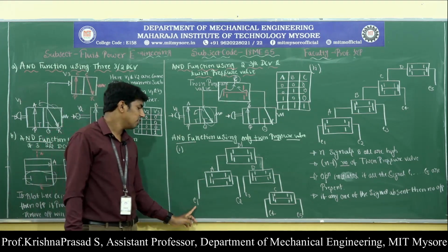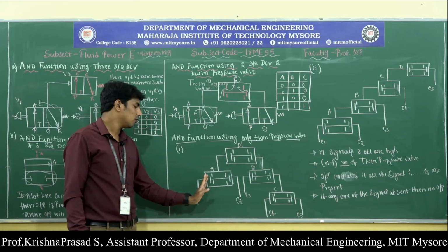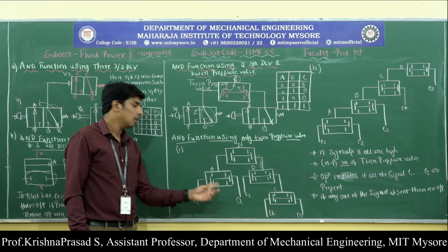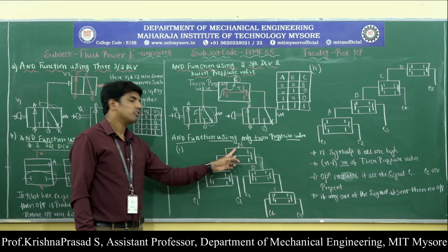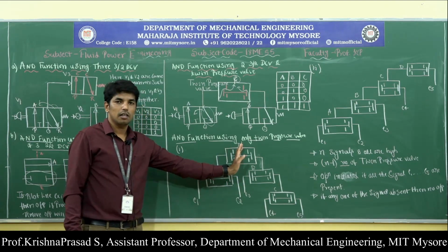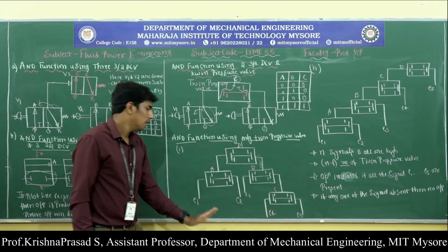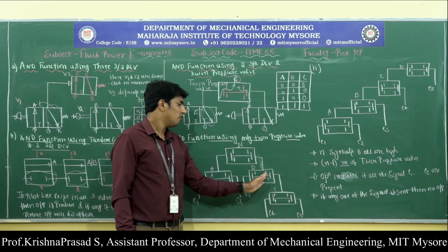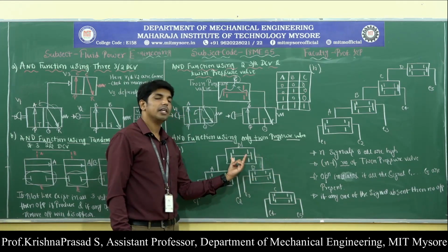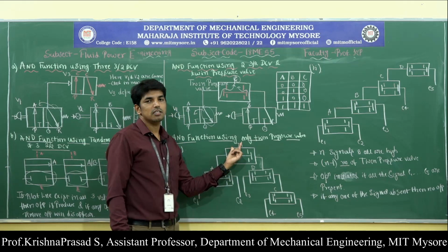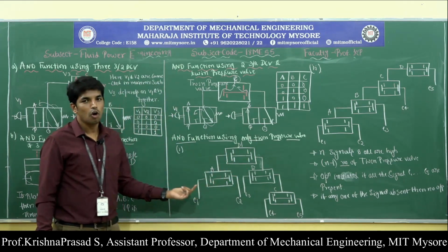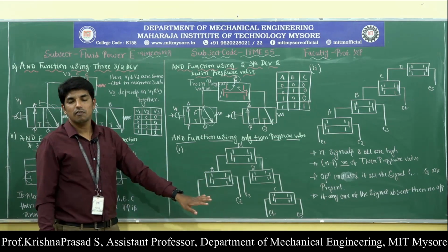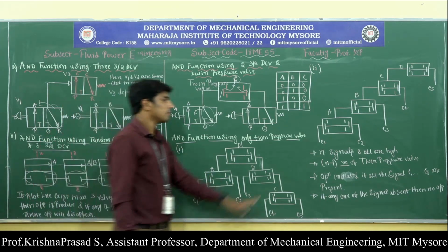Observe here, if the E1 signal is present, then the twin pressure valve shifts towards the left side. If E2 is also present, then it sits exactly at the middle. Then it sends a signal to D, pushes the left side and blocks the flow. If E4 and E5 are present, then this sends the signal to B. If B sends the signal, then it moves exactly to the center, and output is produced. Otherwise there is no output. If all the input signals are present, then only output can be seen, otherwise the output will disappear.